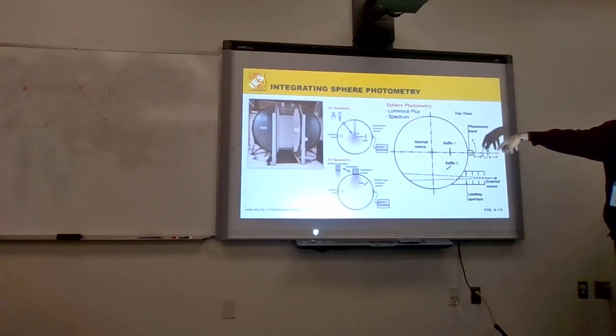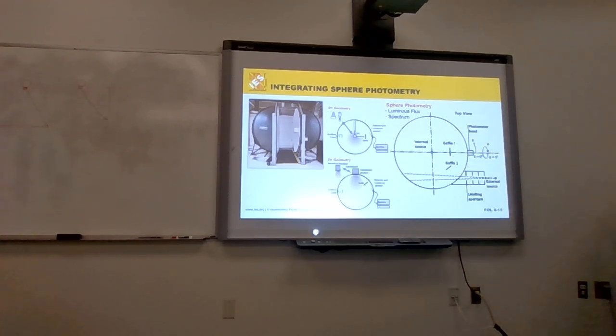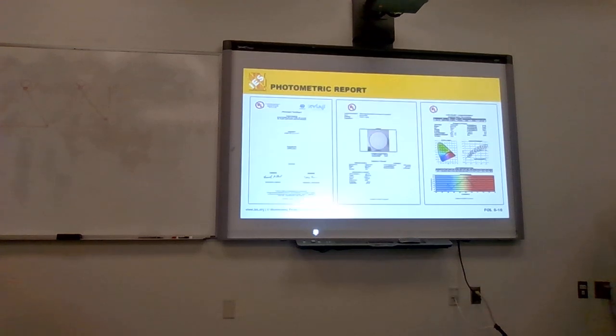Is there going to be a test on what this all means? No. Don't worry about it. Just get the concept. Put a luminaire in the center of the sphere, measure the intensity all around the sphere. What that does is tell us what the lumen output of the luminaire is. Because we sum total all of the candelas and we have a conversion factor into lumens, and then lumens can be converted to foot candle if we apply distance factors.